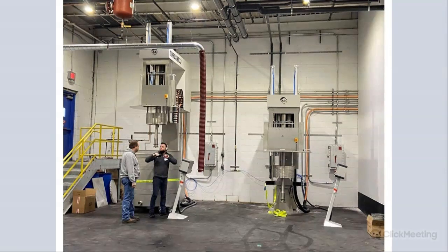Here is a great system called the TML, that's for manufacturing. That's a two-in-one system. So you have your cowl blade right back here, so you can disperse and mill all on one machine. Very, very efficient. You don't have to replace the basket. This is great if you're only producing one color and you want to do a reasonable volume and you don't want to change colors. This is excellent because you pre-disperse. When you're ready to mill, you push the button on the control board, and then the basket comes down, and now you have a fully functioning media mill. You don't have to make any changes whatsoever. Very, very efficient.